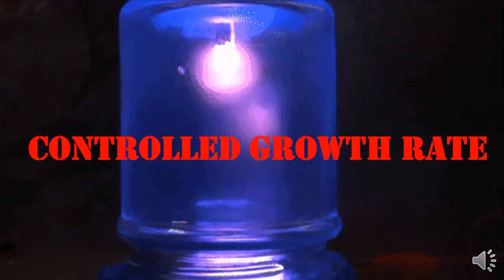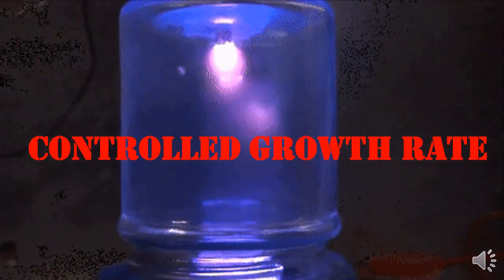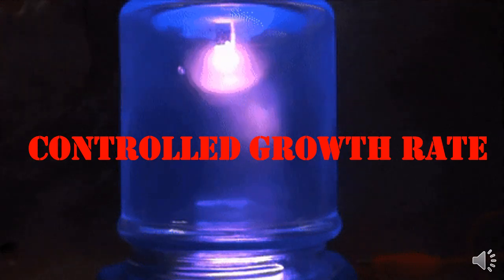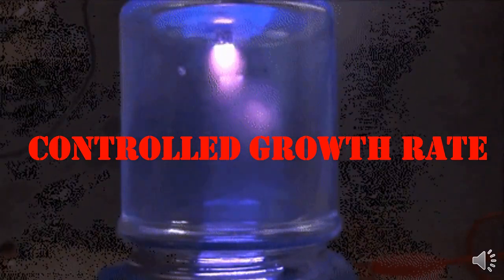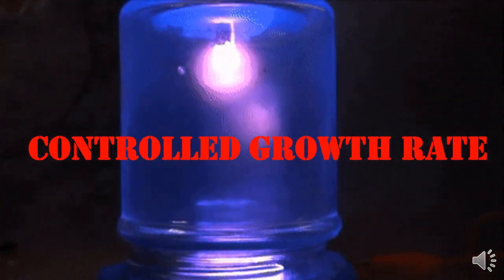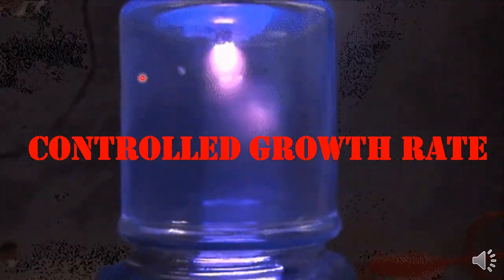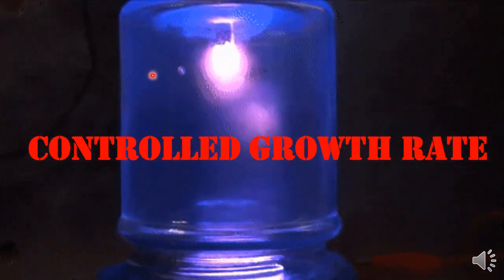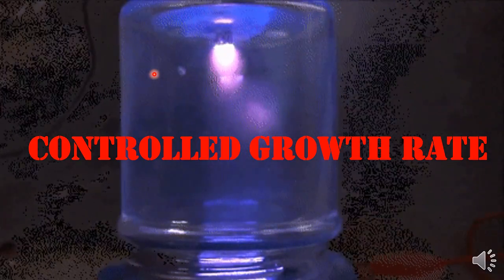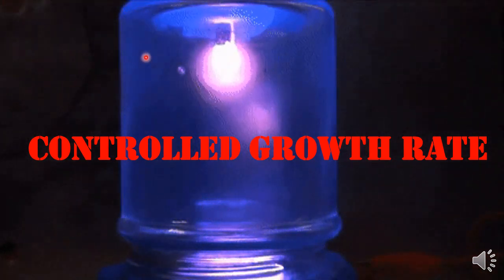Another aspect of the slow growth rate is the electronically controlled setup of shutters, which are present inside the reaction chamber at the top of the dopant container as well as the precursor container. These act in a pulse fashion, and due to this, the advantage of this technique is that we can deposit a thin film in a layer by layer fashion at molecular level. So this technique gives us the window of opportunity to deposit ultra thin layers of different composition in a layer by layer fashion.